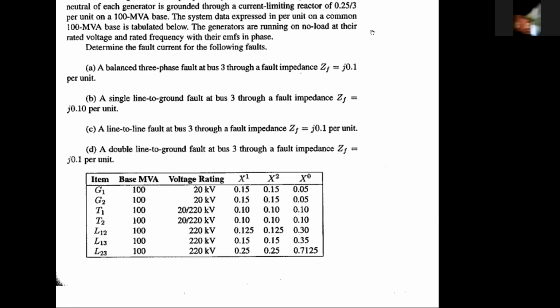So today we have discussed the Thevenin equivalent concept for determination of fault current using four different fault cases. You will be given some tabular information in terms of positive, negative, and zero sequence, and you have to collect this data to generate your Z1, Z2, or Z0, which is applicable for fault current calculation.